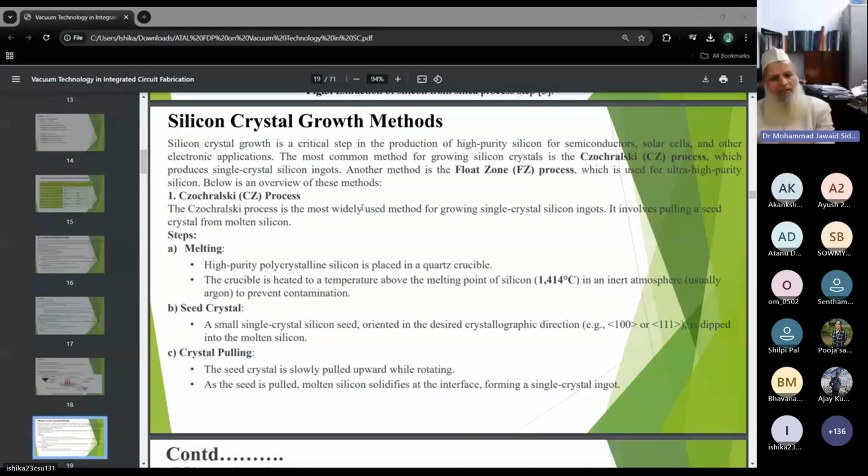Within the grain, the atoms are oriented in a desired position, but in another grain, the orientations of the atoms will be different. Between the grain boundaries, we have discontinuities. So polycrystalline silicon has mobility in between amorphous silicon and single crystal silicon.